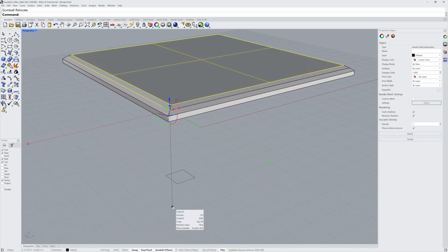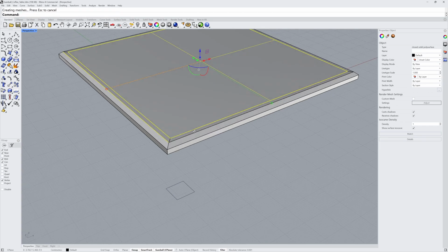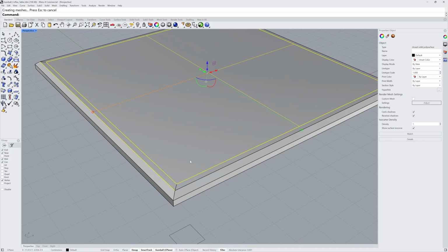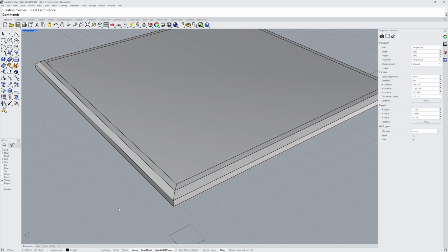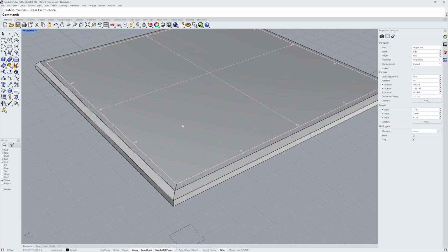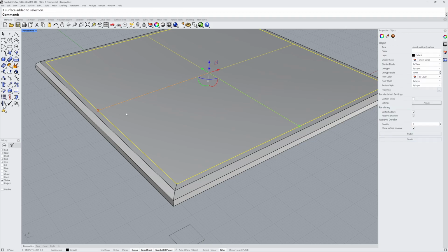If I click and drag on the scale handle for the Z-axis, it will snap to the Gumball origin. This makes those two sub-objects coplanar. They get flattened within that direction. If I sub-object select the interior face, we can scale and hold down Shift to keep it uniform to adjust the size of that center section.